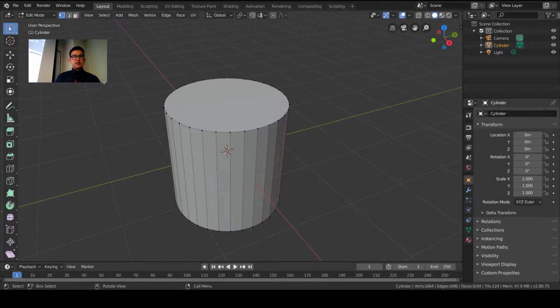So to stretch everything, first I'm just going to cut everything in half. And the best way to do that is on the left here, there's something called loop cut. And if you hold your mouse over these tools, you'll see the descriptions. So loop cut, it says it cuts a mesh loop, and you can slide it around to cut a loop around different things. So let's click on that. So once you have this tool selected and you hover over things, you'll see these yellow lines that show you where the cuts are.